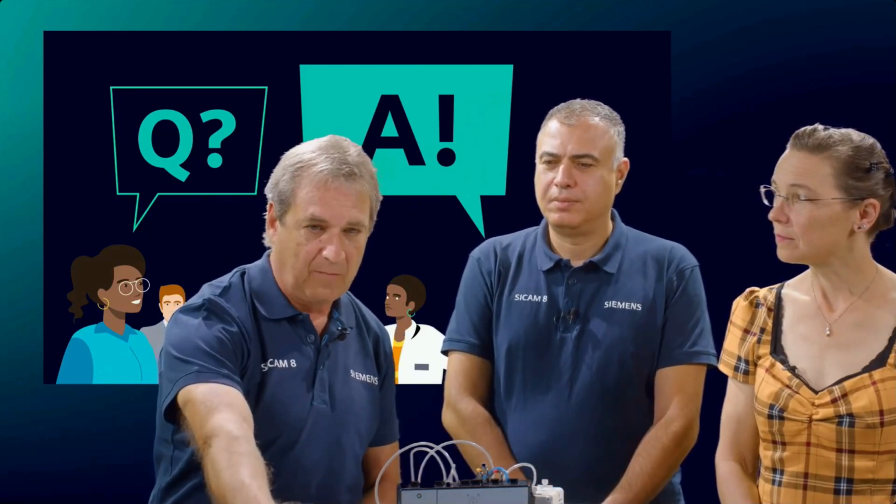If I may add, at the same time, for instance, using IEC 60870-5-104, you could transmit using the LTE modem to a SCADA system. And on the other side, using this wired interface, using IEC 61850 to communicate to protection relays. And please allow me to comment, as far as I know, we are the only one who can do this for this voltage level. Impressive.